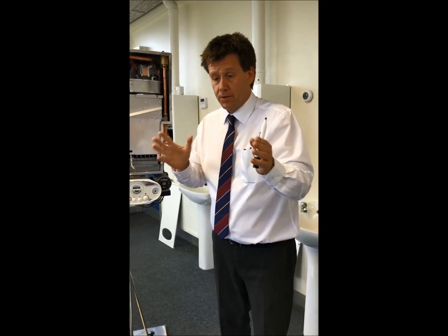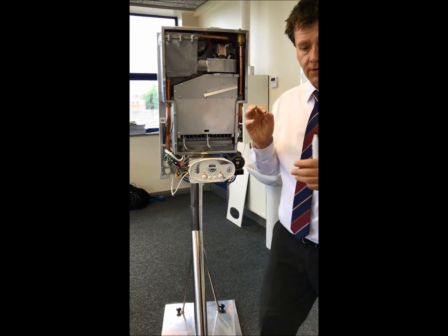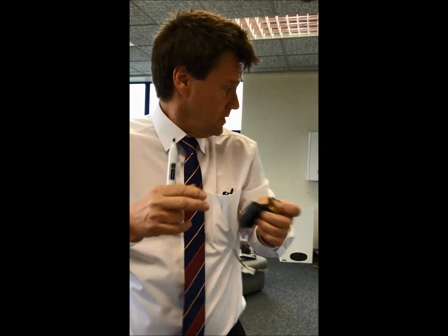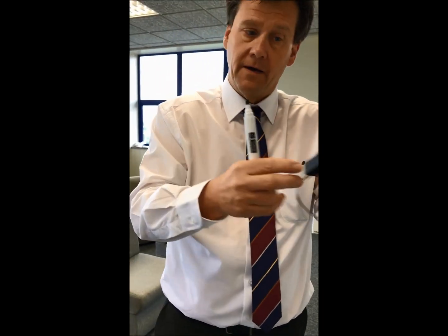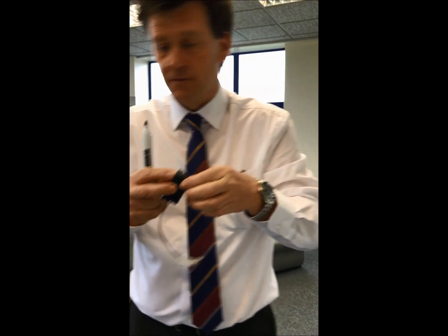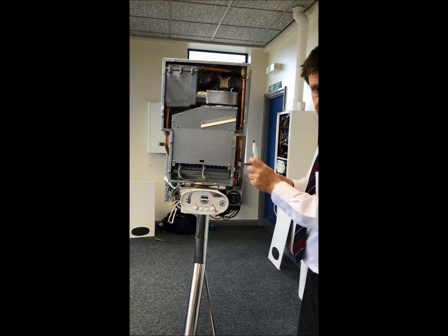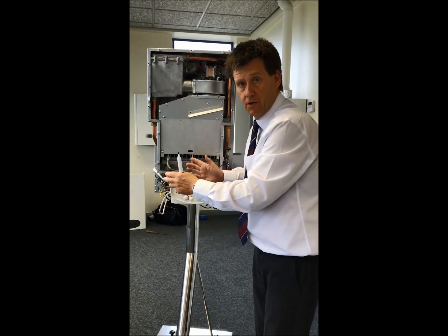The pump comes direct from the circuit board in older technology like this. As we move on, some boilers may have some device like this. They may have a pump proving switch, where if the pump's not energized, then the sequence can't continue. But let's look at boilers that you're working on without flow switches and without a pump proving switch. So we switch this type of appliance on, and the pump immediately energizes, and the pump comes direct from the circuit board.